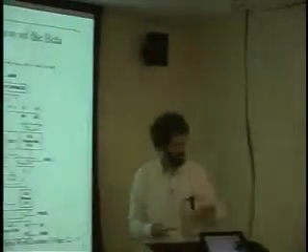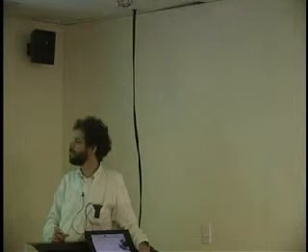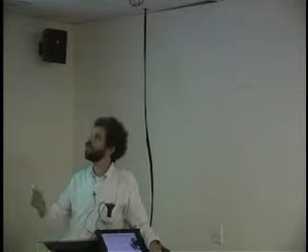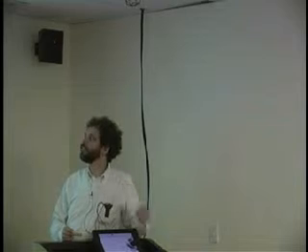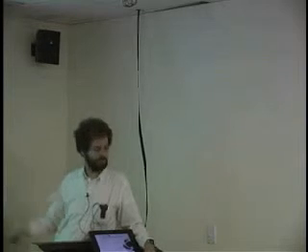And is it the act of the PC register getting written that takes us back up to the top and makes this happen? Absolutely right, yes. Because otherwise the value of the PC wouldn't change, and everything would just sort of be static. What's neat is that you'll get to see this in action with BetaSim, because you'll be able to draw these things out and you'll get to watch the data flow through.